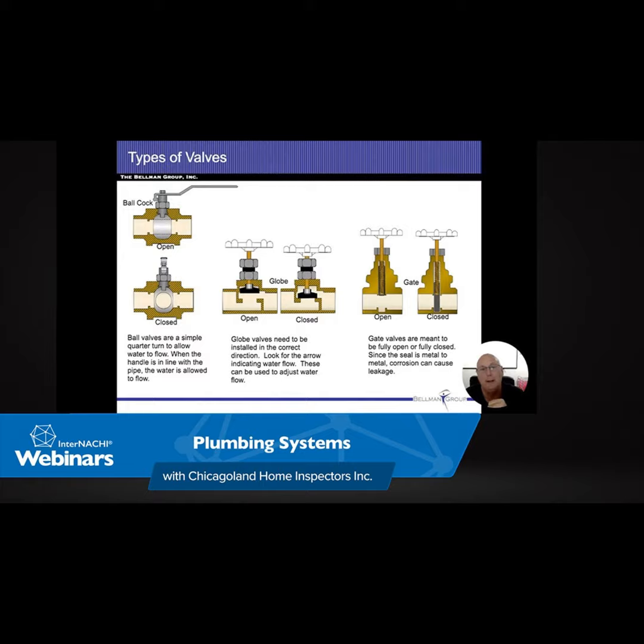Instant hot water heaters. I did it. Instant water heaters. They're becoming whole house ones. I put one in my house, and me personally, I think it's phenomenal. Never run out of hot water. We could take 2 showers at the same time. The drawback is they do require maintenance. And they do need to be flushed, and they have cleaning kits that get in there because the pipes are so thin on those that there's a lot of calcium buildup on it. So it is something that needs to be done.